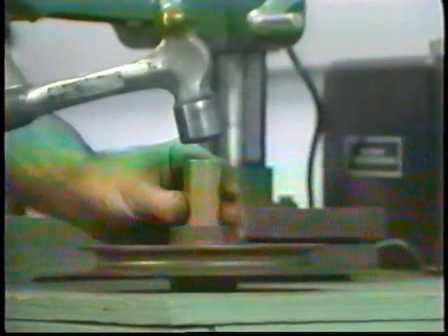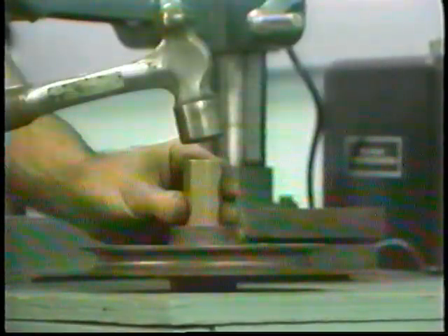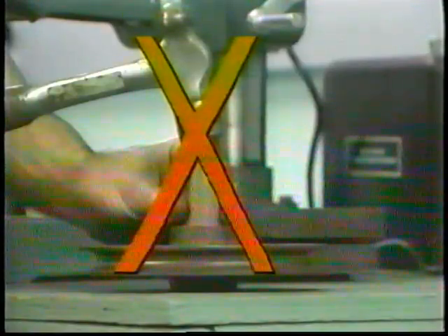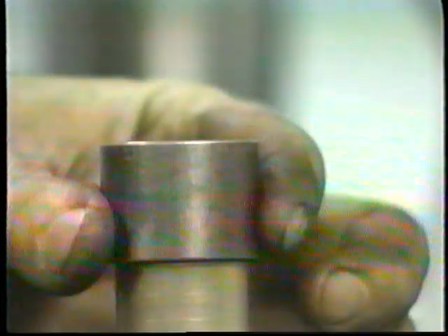Never attempt to drive a bearing in place with just a hammer. This will distort the bearing surfaces, probably making it impossible to mount the bearing correctly on the shaft or in the bore. A pilot driver, like this, will support the bearing inside and keep it from being distorted. However, whenever possible, you should use a press. Carefully align the press ram with the bore, and use a shouldered arbor or steel plate to make certain the bearing remains aligned with the bore as it enters.